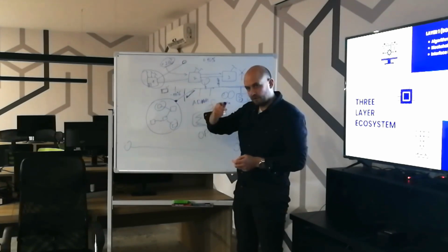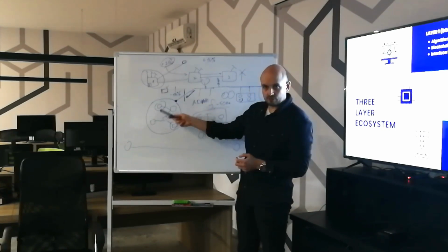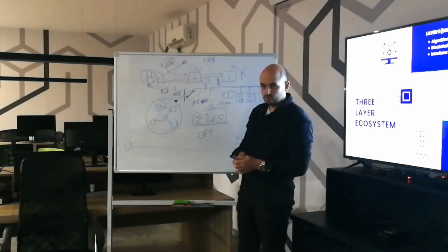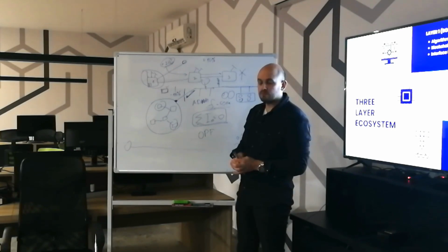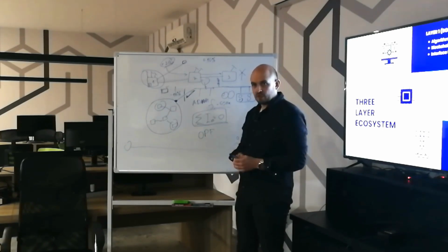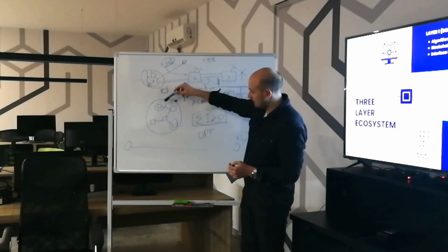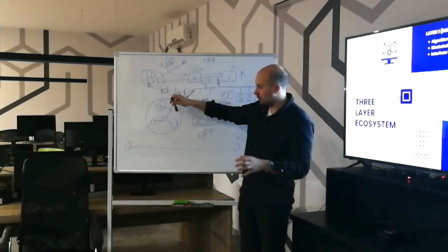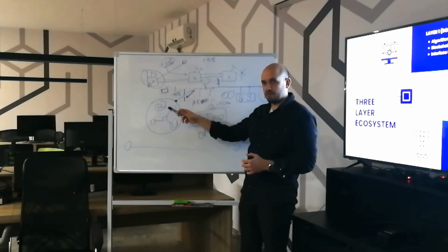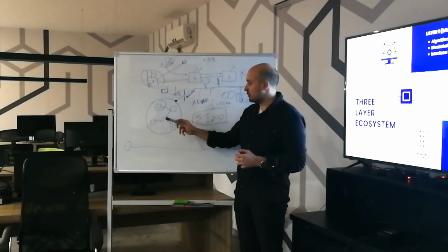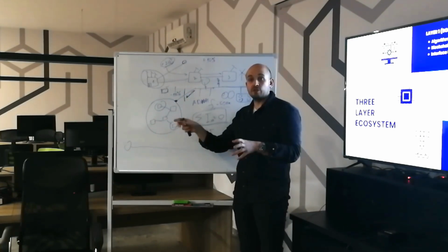If I understood your question correctly, exactly that. My question is, are we going to lose the whole microgrid just by losing 10% of the supply? Isn't it better to switch off certain customers, to say, today, now you can't get electricity? Exactly. Maybe I didn't explain it clearly, but exactly that. We can assign different status or importance to the objects participating in the microgrid. So we cut this one off because it's a private household, or we can implement different restrictions during different periods of time.